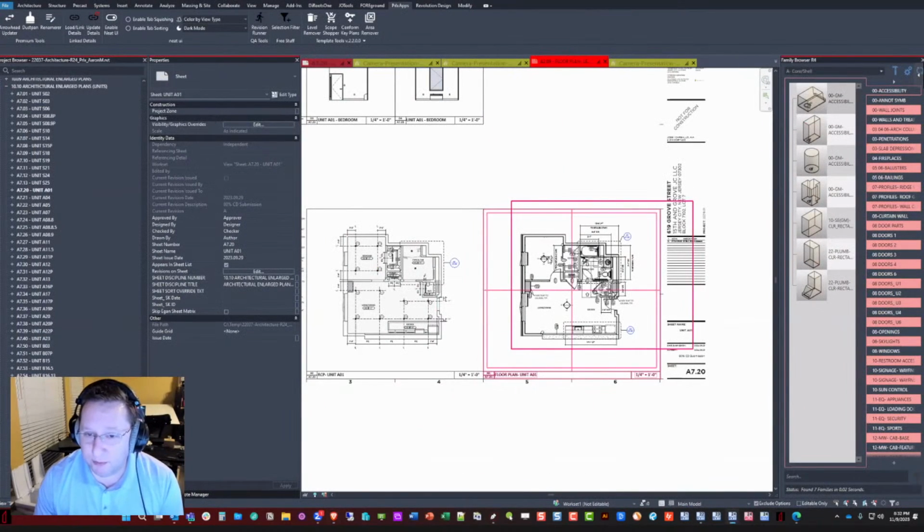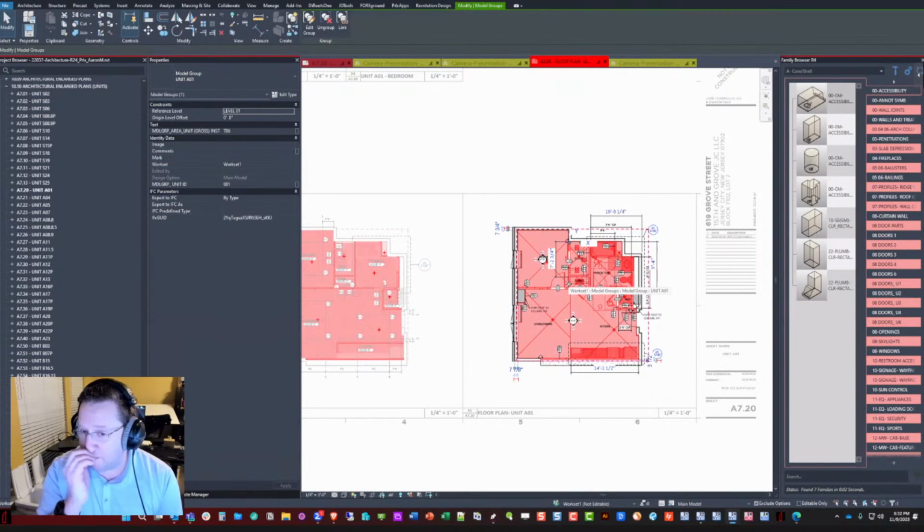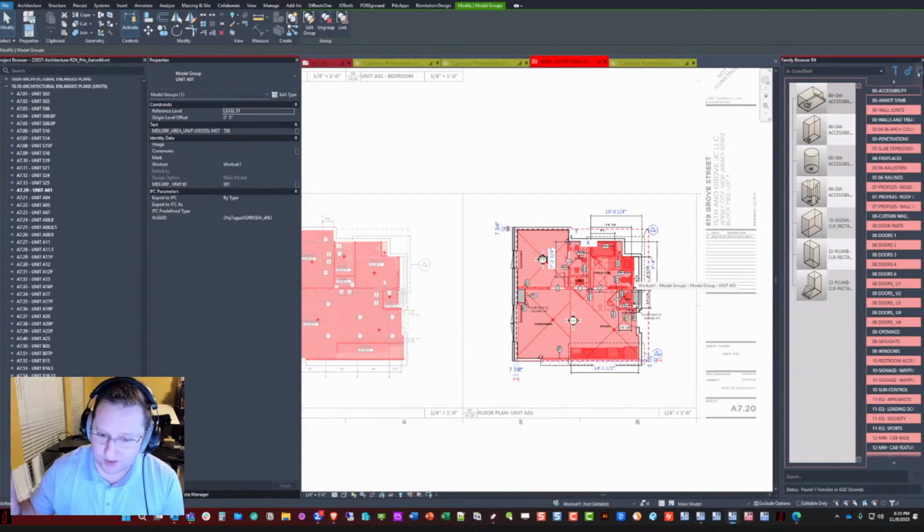I generally always group these units and start copying them around as the real thing right away. But we have done some workflows with some clients where basically they trace the interior of the unit with just a floor. So there is just a floor, and we call it unit A1. Because in early design, when you want to throw units around really quick, just throwing around a sketched floor is really fast. And no matter how lightweight you make that group, copying it around is always going to stink.